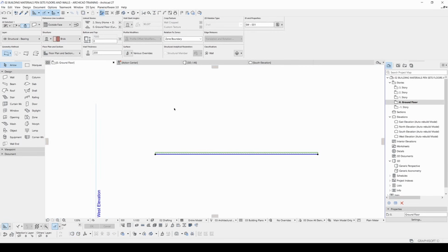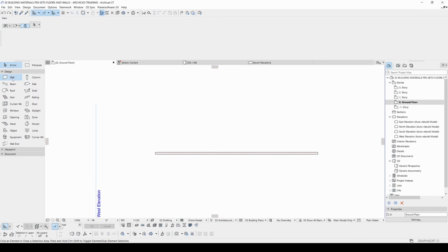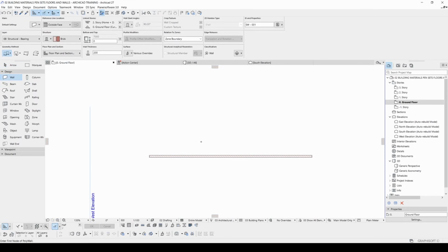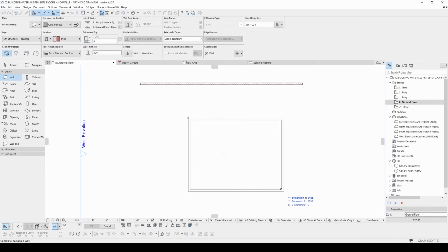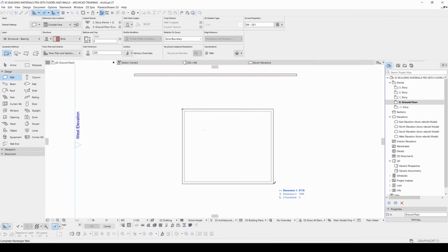let's say that we are going to create a room. Let's click the wall tool, or if you hit Alt, you will just copy these settings. And after that, as we use the line system, that's why it's important to watch the first lesson. We can use this polygonal method, we can use the circular and rectangular from this menu. And once we click, we will click our second position to finish this rectangular room.